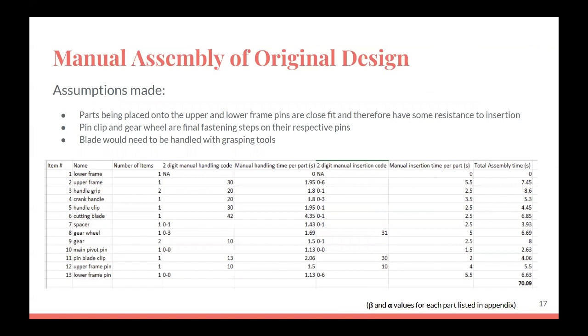And the third assumption made was that the blade would need to be handled with grasping tools because it's a sharp object. And after going through the estimation, we found that the manual assembly time of the original design would be about 70 seconds.